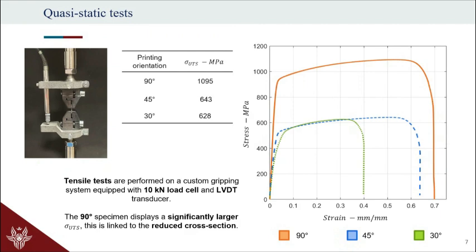So a clear definition of what a cross-section is, is extremely important, because for 90 degrees we have a cross-section which is almost half of the nominal one, meaning that the ratio between the surface defectiveness and the actual cross-section is very important. Therefore the load-bearing cross-section is a fraction of what we see, and we cannot compute it properly. So this is an open question. I just want to show you this result in order to start a conversation on the topic.